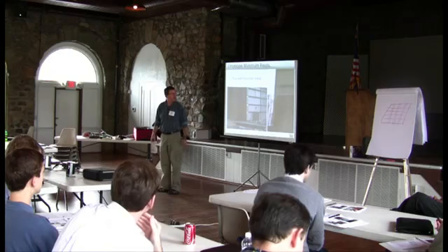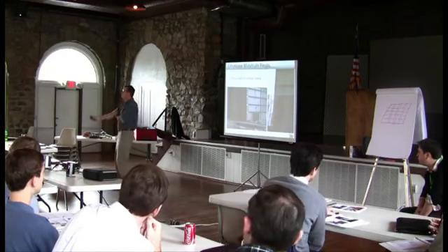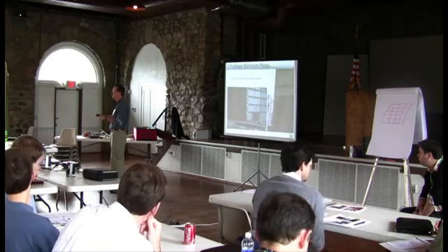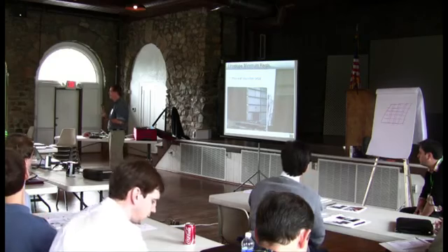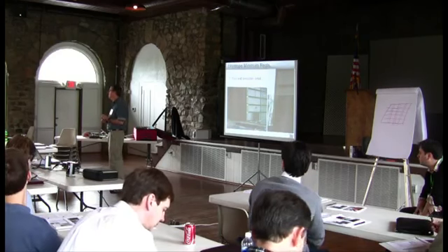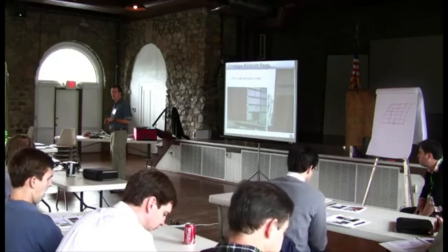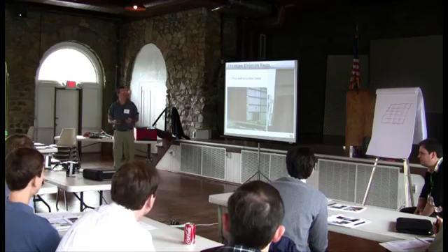Okay. And your assembly that you're describing, I think, from a code standpoint, you get the R value on the outer part. You don't necessarily have to put anything on the studs on the inner part. I think that might be another way to approach it. Or you could go beyond code to say, hey, we're going to work better. Questions, comments? Took a while to get to this picture, but now everyone's dead. No one wants to talk.